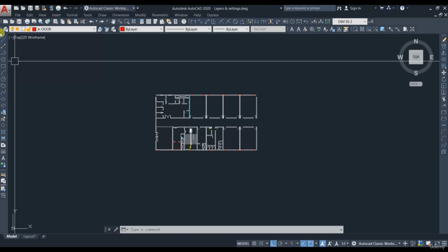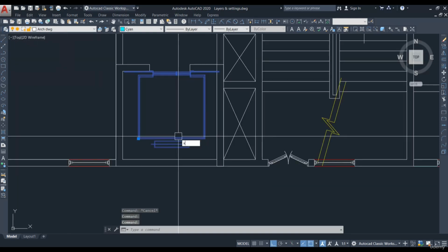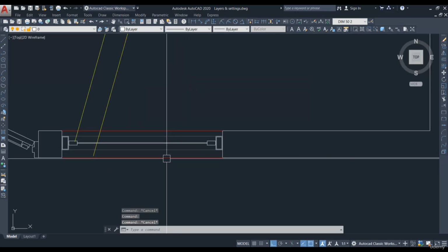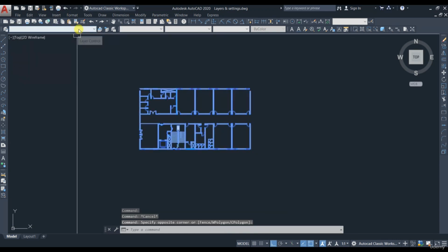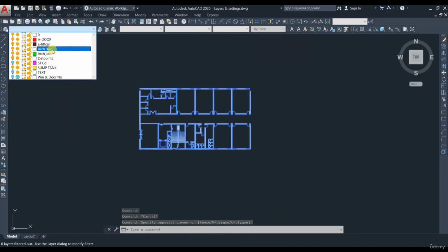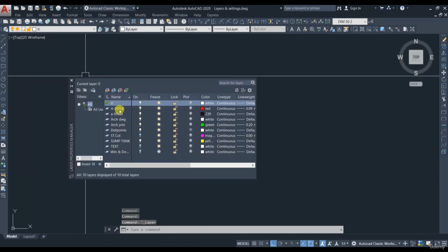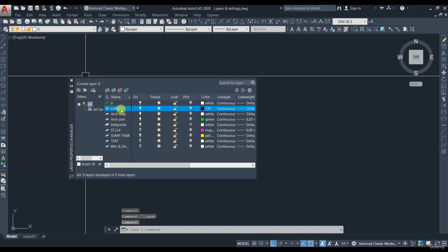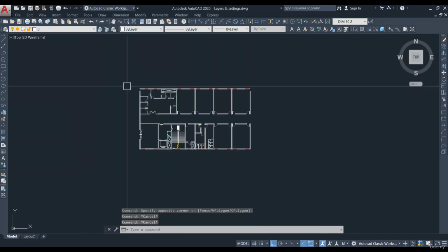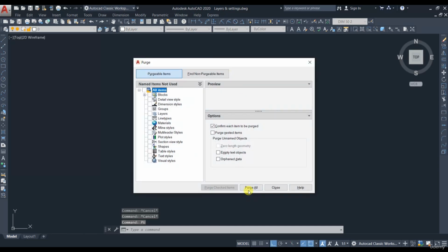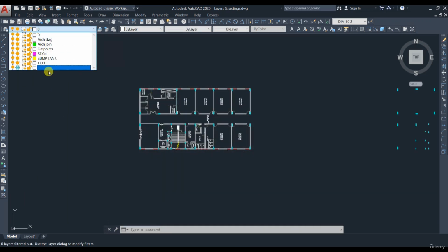Now let's see how we can delete the layer. This one is a block now. Explode it. If you check, some others will be in a block, so that is why it is showing all the layers. Just go to this, select this, and then put it under architectural drawing. So now go to this and then select. See, now you can delete these layers. Before that you have to use the purge command. Give purge all. See, we have reduced many layers now.